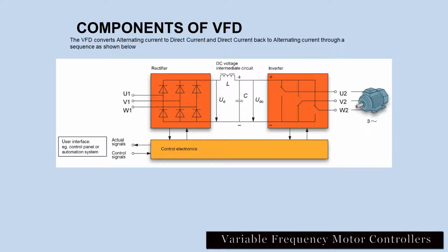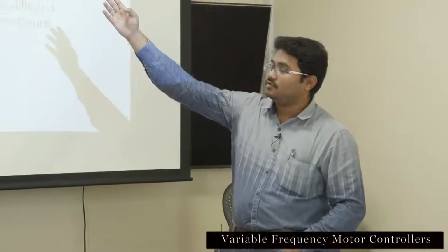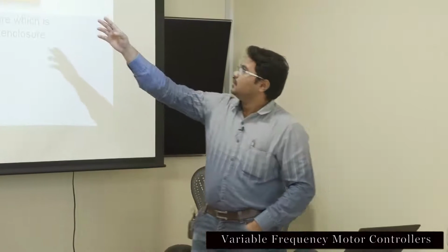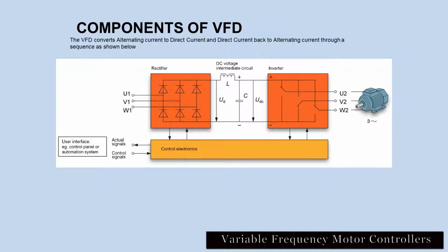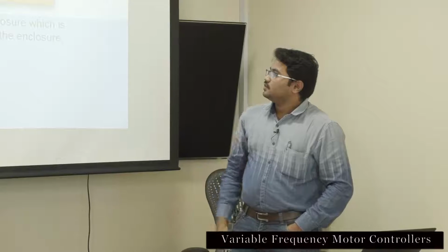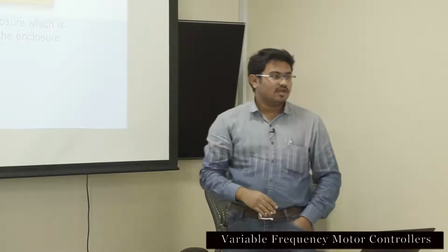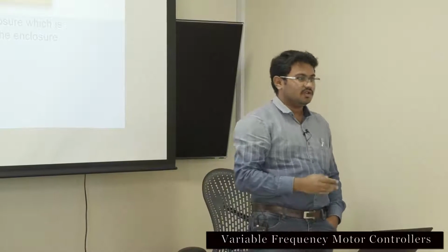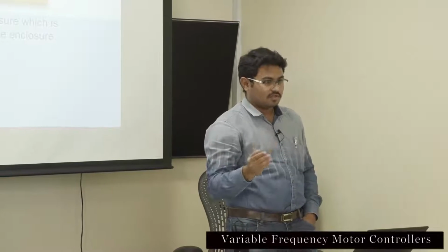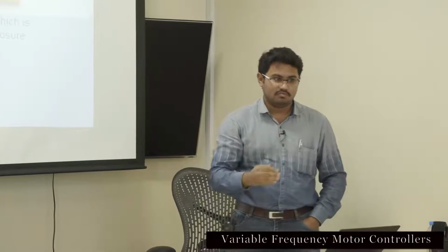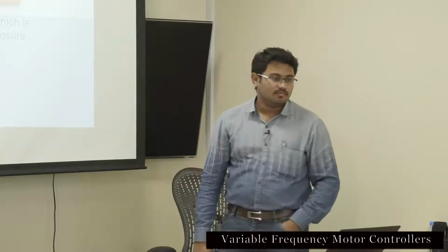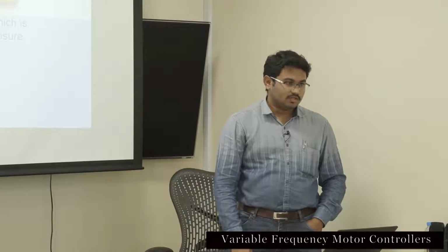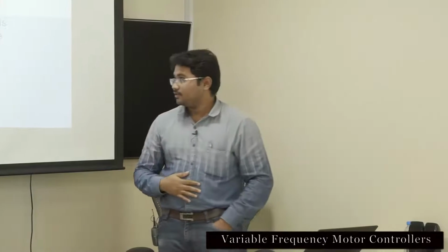And here are the basic components of the VFDs. For example, we have a diode rectifier device, and you have a swinging choke in between. This does the harmonic mitigation, and then you have the capacitors in between which will filter the DC ripples. And then you have the inverter section, where we are using IGBTs to invert for the motor. And in some cases you can find output chokes where you have a very long cable distance, for example 300-400 meters between the drive and motor. Then you will have a DU/DT choke between the drive module and the motor, which will reduce the voltage spikes at the motor end basically.